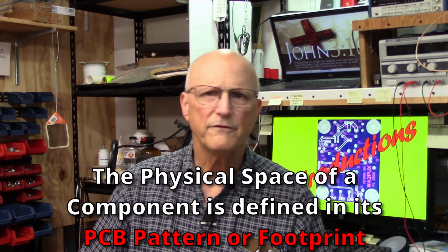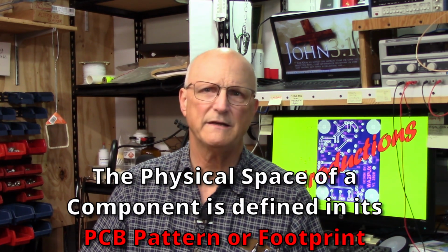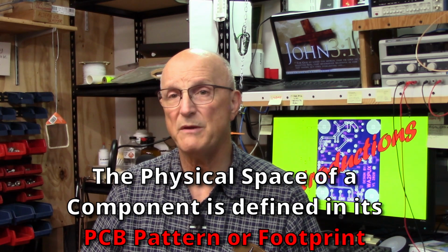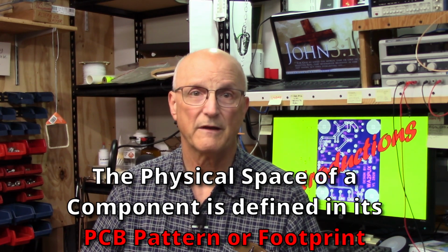Like the PC board itself, the parts we put on the PC board and that appear in our schematic are very physical entities. Each of these parts consume physical board space and have physical pins in specific locations. Some of the parts must be oriented in a very specific way for them to operate properly. All of these physical realities are baked into what are called the PCB patterns or footprints. All of the parts are then arranged on the surface of the PC board.